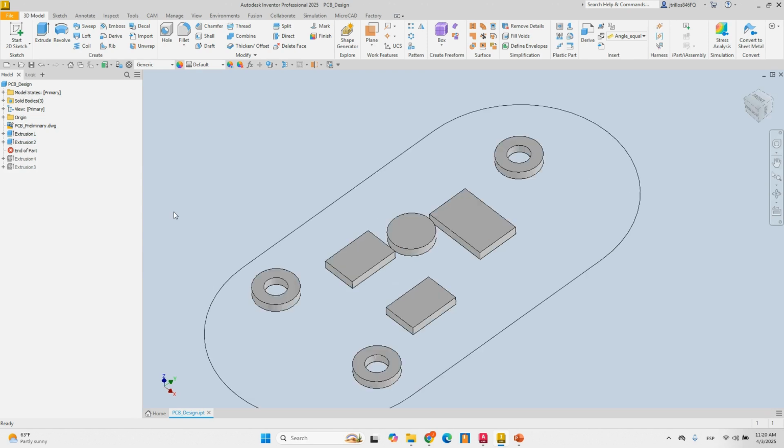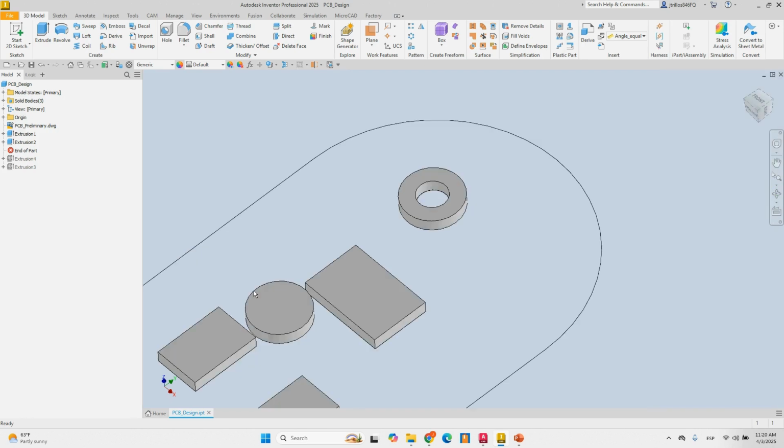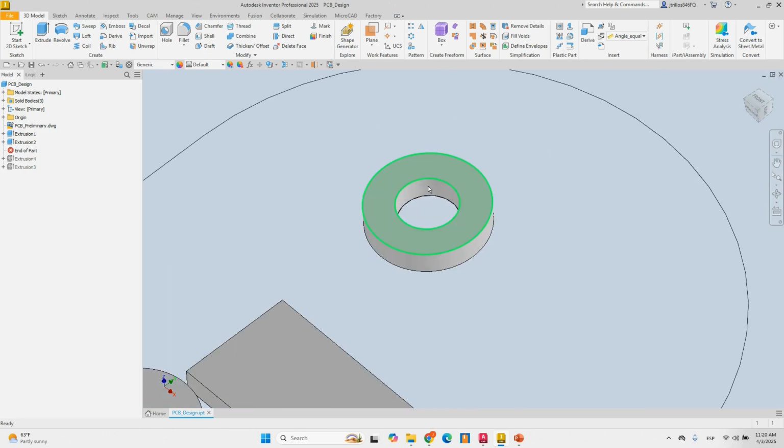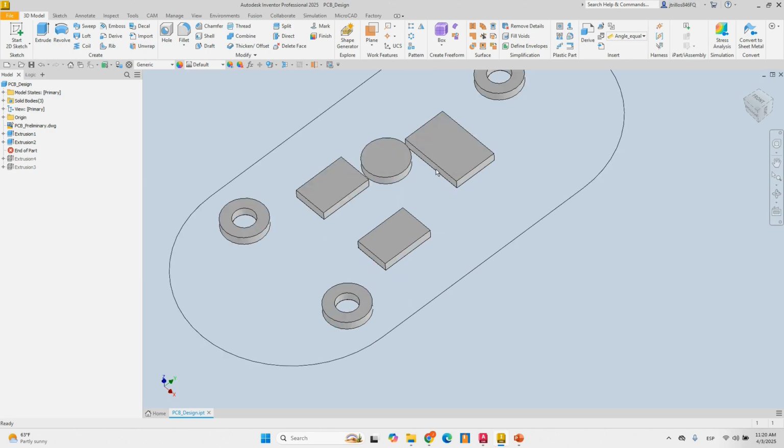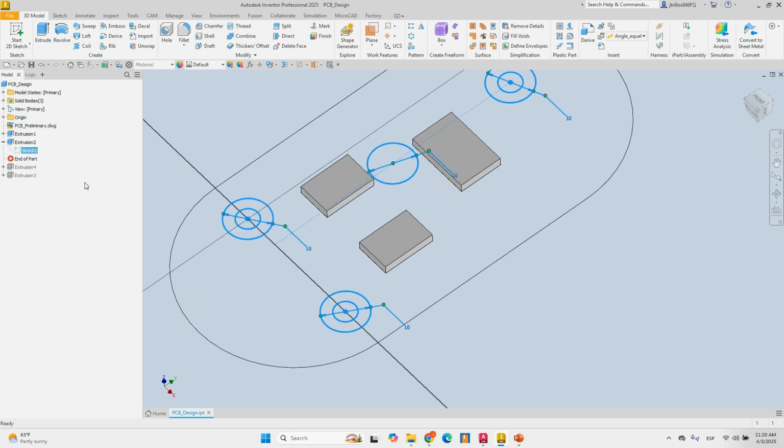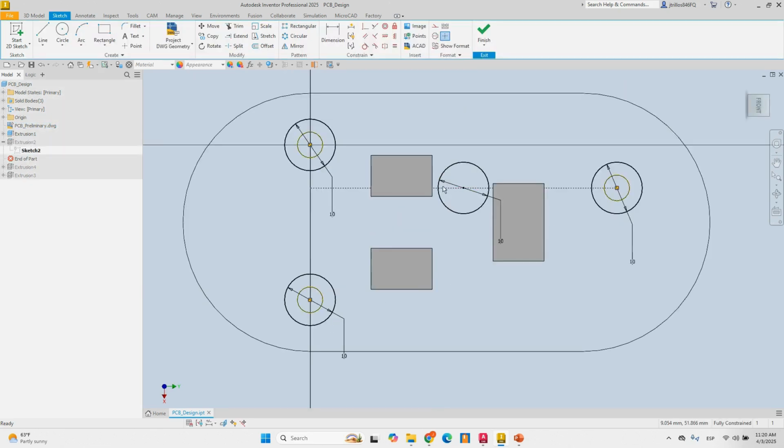This needs to be present in my PCB, right? These holes right there for mounting should be present as well, so some material should be present around my holes as well, right? Same for this contact point right here in the middle, okay? Maybe because I updated my drawing, this changed as well in here, so I'm gonna modify it a little bit. So this is gonna be my pressure point, basically where I'm gonna place a button or something like that.